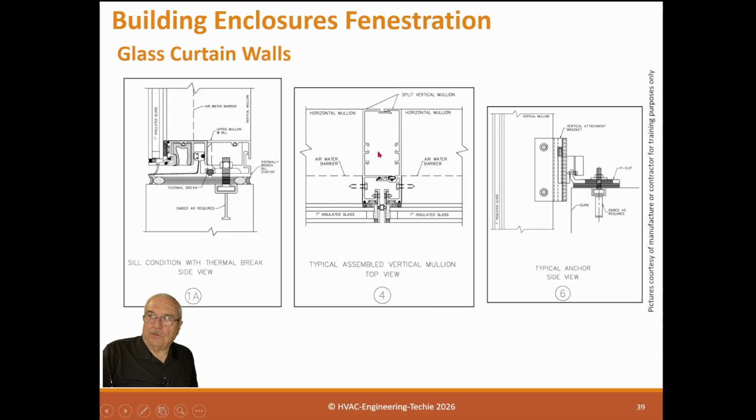One thing I found out the hard way, which is strange, is that this member, which is going horizontal, and this member, which is going vertical, are not air sealed between each other. I have done buildings where I've pressure tested inside of the building here, and the leak went through here, went through the horizontal until the next room on the other side. Because these go between the structure, it was a leak we could not seal.